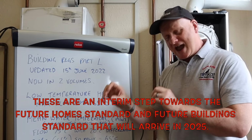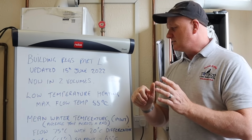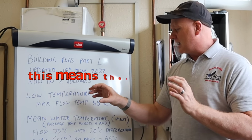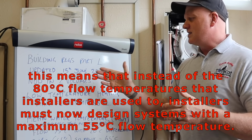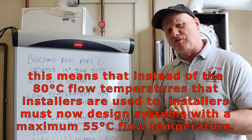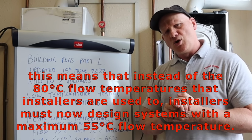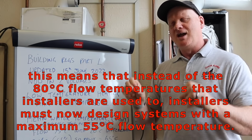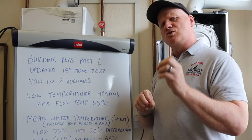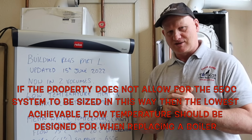They did, but now replacement boilers are in there. And we're talking about low temperature heating now within the building regs Part L. It's saying our maximum flow temperature on our central heating should be no more than 55 degrees and our heating systems should be designed for 55 degrees.